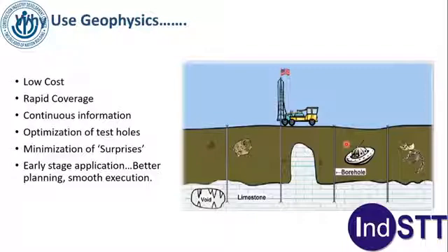But the tools which are available are GPR. This is an image from GPR. You can see the voids here. Electrical resistivity imaging. This is the image from electrical resistivity imaging, which shows boulders, which shows the zone of water accumulation. MASW, microgravity. This is one image from microgravity. Here is a void here.